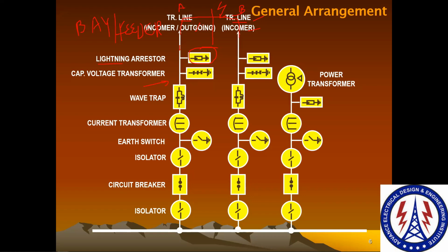There is also one other case, overvoltage. Due to switching or something else, overvoltage can happen in our substation. This overvoltage can be grounded, so it will not affect the downstream equipment of that particular feeder or bay. For that reason we have the LA at the first point.